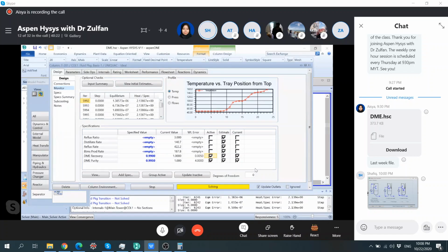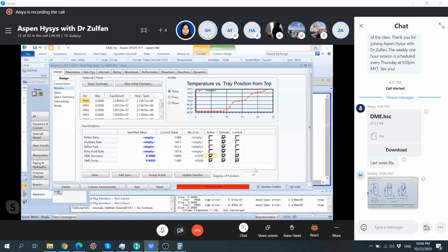Very pure DME, 100% DME recovered, but we want it in the mediocre range. Yeah. So now I am suspicious about stream 9, because in the mass balance we should have methanol as well, right? The unreacted methanol, because if we see, it doesn't converge.